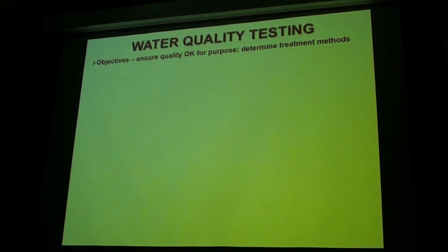They should be kept at constant temperature, preferably in the fridge. If you want to know what the water temperature is in the bore, then measure it as it comes out of the ground. Same with the pH, measure that as it comes out of the ground, because that'll change through time. All these other things you just seal up in a bottle and send to the lab, and they'll do various tests to tell you what they are. But earlier on, when we were doing our initial testing, we just tested for a small suite of elements, because we were just interested to see if the water was possibly drinkable, and wasn't near the sea or near a hydrothermal source or something like that. Okay, that's all we did initially, and it passed.